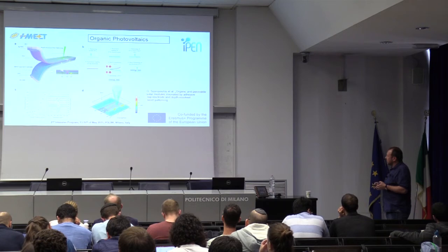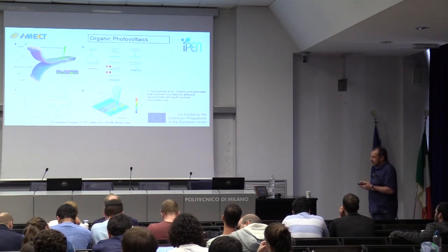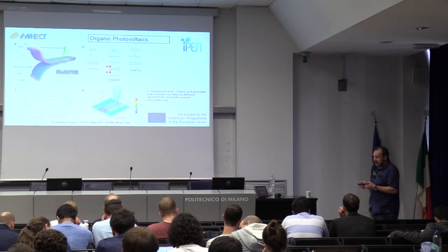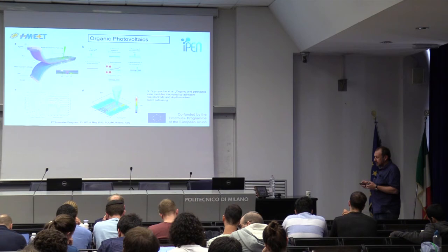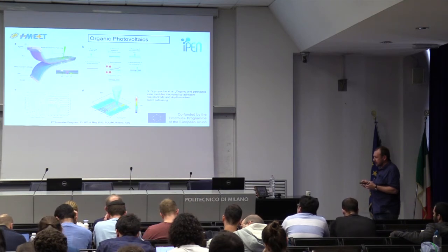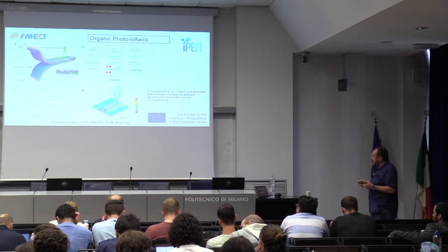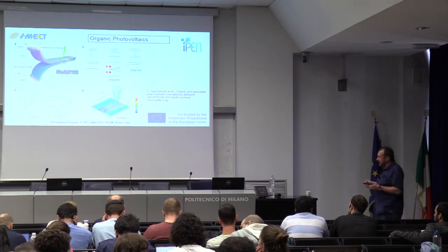And now how do you do the structuring? You can do the structuring of these P1 and P2 grooves already in this lower part of the solar cell, and then you put on the top part with a transparent electrode containing silver nanowires here. And the trick was to do the structuring of the P3 line through the PET foil.